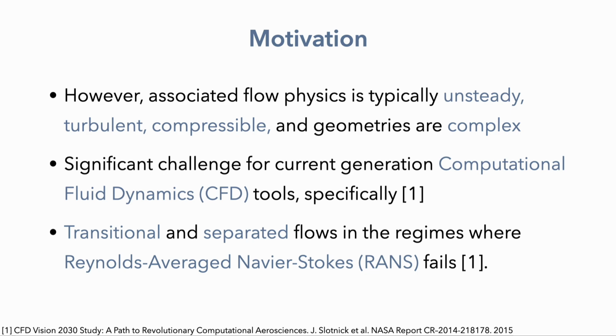Now, from an engineering perspective, this is challenging because the types of flows that we deal with in aerospace engineering and aircraft design are typically unsteady, turbulent, and compressible, and the geometries are complex. So for example, the landing gear that I showed on the previous slide is a highly complex geometry. And it turns out that the combination of all of these is a significant challenge for current generation computational fluid dynamics tools. Typically what I'm talking about here is the Reynolds-averaged Navier-Stokes approach, where we solve for the time average of the Navier-Stokes equations.